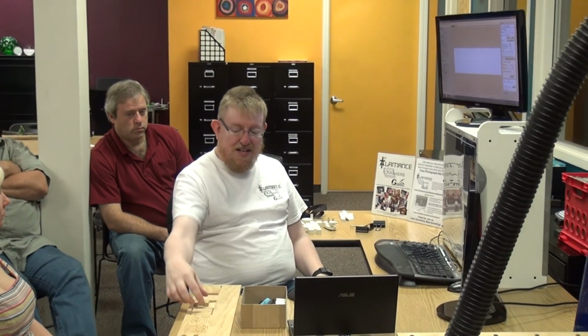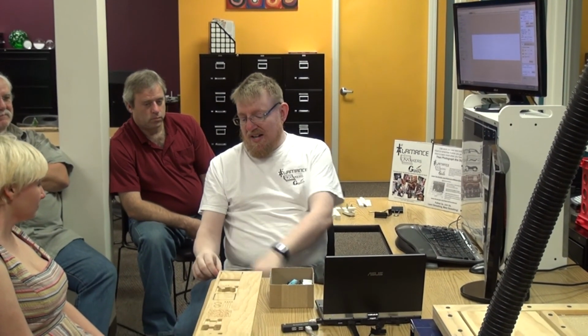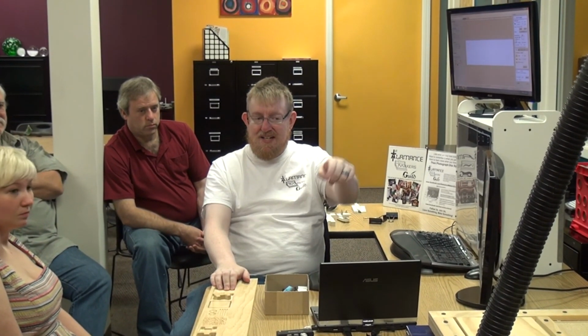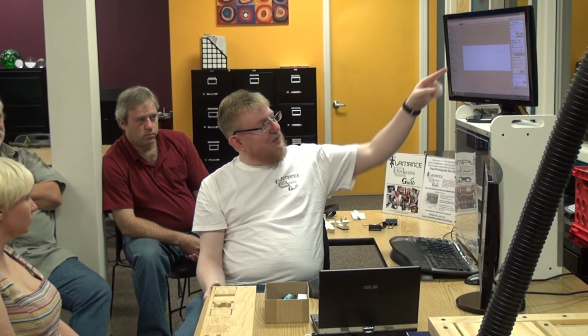So this I'm going to cut out, and I'm going to add tabs to it. And you can adjust the tabs. I'm cutting kind of a small piece here. My router bit's a 1/8 inch bit, so I'm going to leave 1/8 of an inch tab width and height on it. Now, when you're doing this, you can be very accurate X and Y to your 0 point. Your depth depends on how good your zeroing is, and I'm going to cut all the way through.